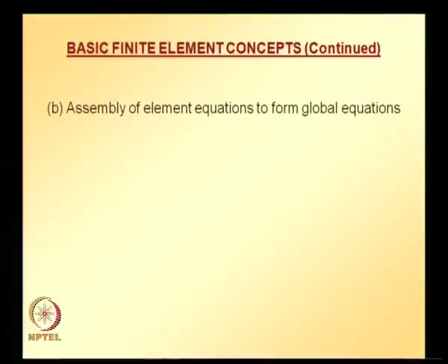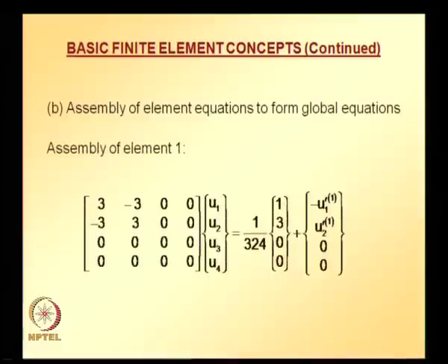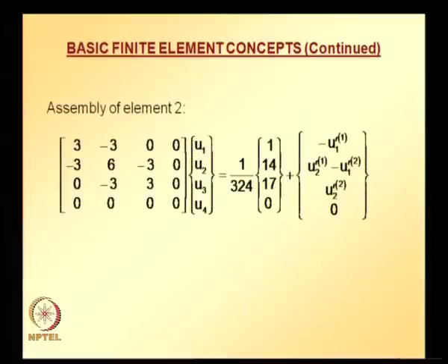Assembly of element equations to form global equations. This is similar to what we have seen for variational method or Rayleigh method. The first element contribution goes into 1 and 2 rows and columns of the global equation system. Second element contribution goes into 2 and 3 rows and columns.